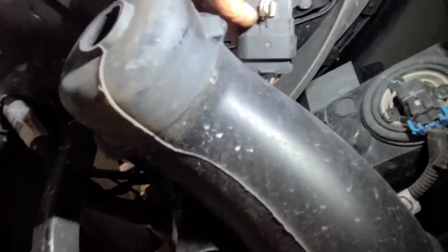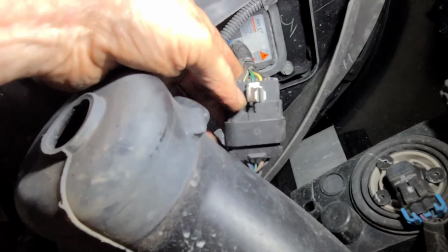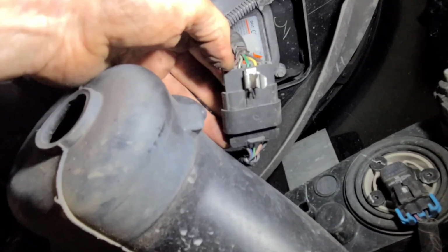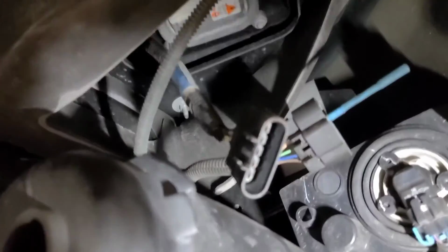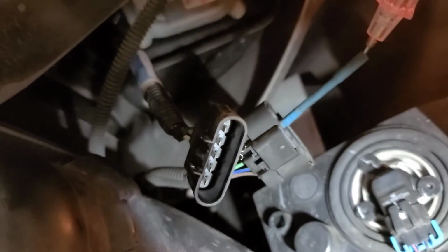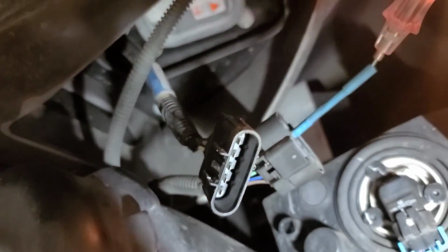Well, most of the time the alphabet goes A, B, C. So that would be B. So let's backpin it. I decided to take the connector apart to inspect it. And on this end of the connector, which appears to be coming from the body of the vehicle, I have power on that tan white wire. Then it becomes yellow. So that tells me there must be another sub harness up here.